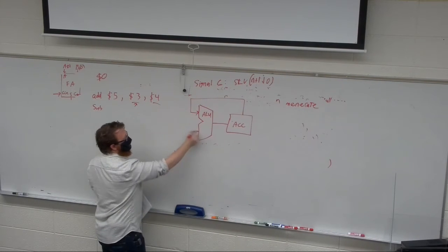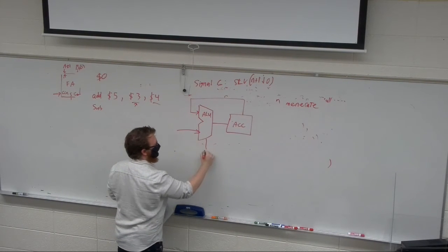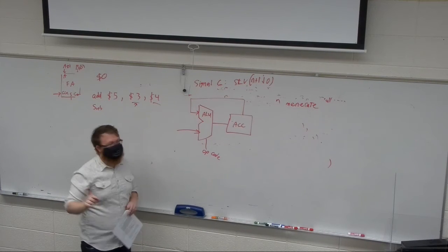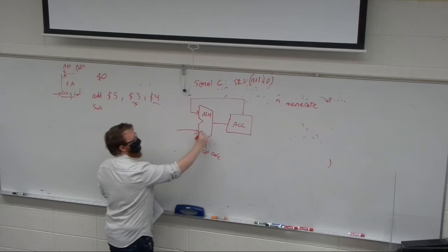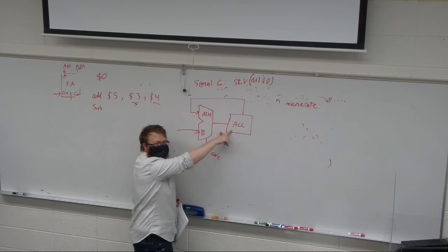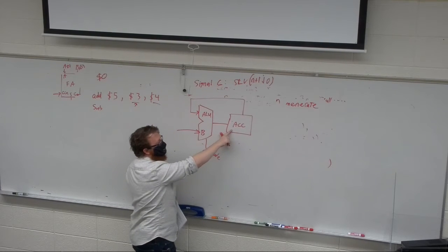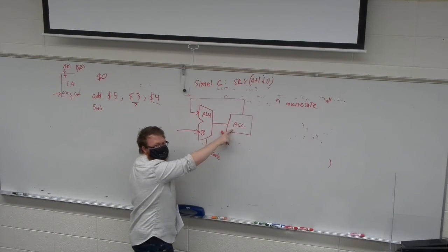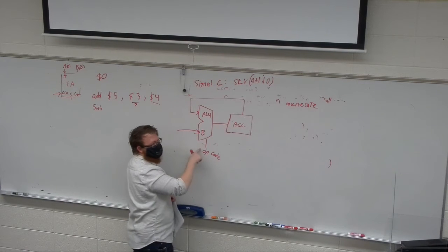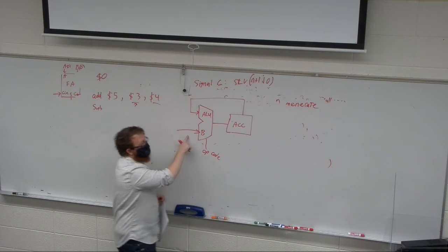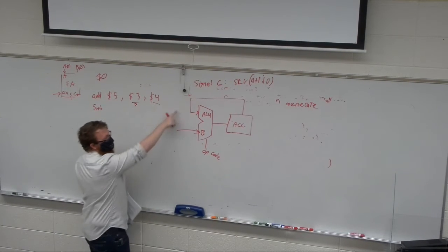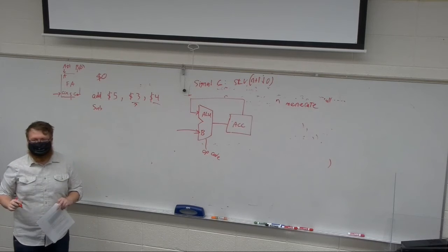Right. So this is the arithmetic logic unit. And the one you guys designed only takes B out of memory and then adds it to the accumulator, or not. But if it wanted to do 2 addresses, it would have to send the load command, which would take B and store it in the accumulator, and then the add command with the new address, right? This one does not have that feedback. And it would just tie up these 2 various registers and store the result in a different register in the MIPS.